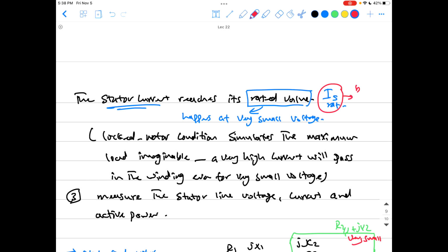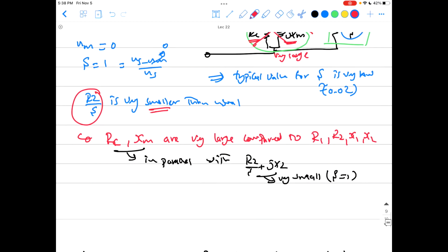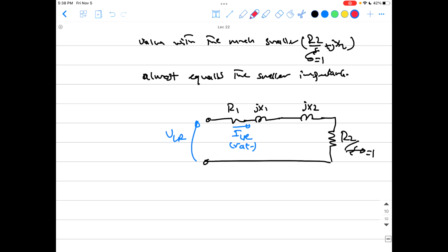because it is the typical working current of the machine. Okay guys, so we're trying to simulate the actual working condition of the machine. Okay, keep that in mind because that's important. I can give you this problem and not tell you how much current is moving in the machine in the locked rotor test, and it's not missing data because you should note for yourself that the locked rotor current equals the rated current, so you can just look up the rated current of the machine and use it. Okay guys, so yeah, keep that in mind.